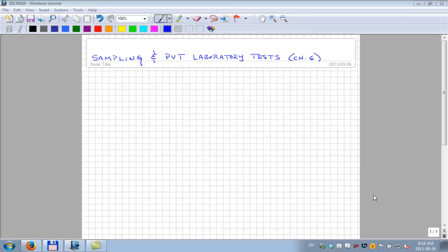So there's only a certain pressure, temperature, composition space where you can make measurements. And in the actual reservoir production system into the surface, you may go outside that pressure, temperature space and need properties outside where these measurements have been made. Therefore, we have to build models, typically matching the measurements, but models that are more general character.